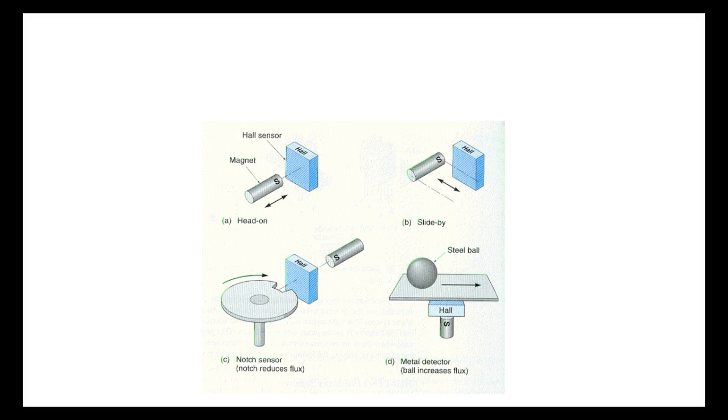So that's the biggest advantage. So it's electronic, so your reed switch is going to have to be a certain size. So those big old metal ones mounted on the side of those cylinders are probably reed switches. On the cylinder that pushes the block out, the little tiny sensors, them are probably what? Them are probably Hall effect. So electronics can be what? A lot smaller.